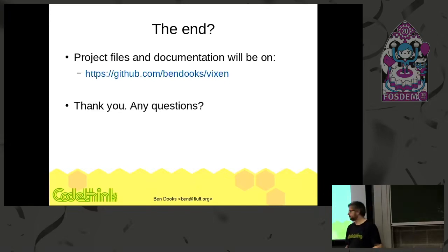So at the back there. The original card has RC type, resistor capacitor, and Schmitt trigger for implementing the states. And you proposed we can use a PLL to multiply the clock and some shift registers.